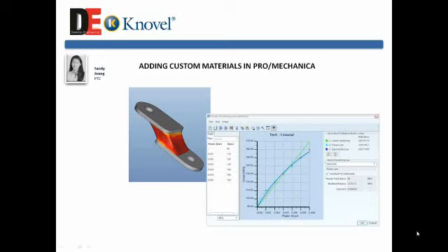So this slide here actually shows you how in ProEngineer today you can take the test input data from a material, we'll call it a specialty polymer composite, that's used here to bond these two metal sheets. We're looking at the stress strain properties, and the software is automatically calculating the Young's modulus, which would then be used in some higher end CAE analyses within ProEngineer.